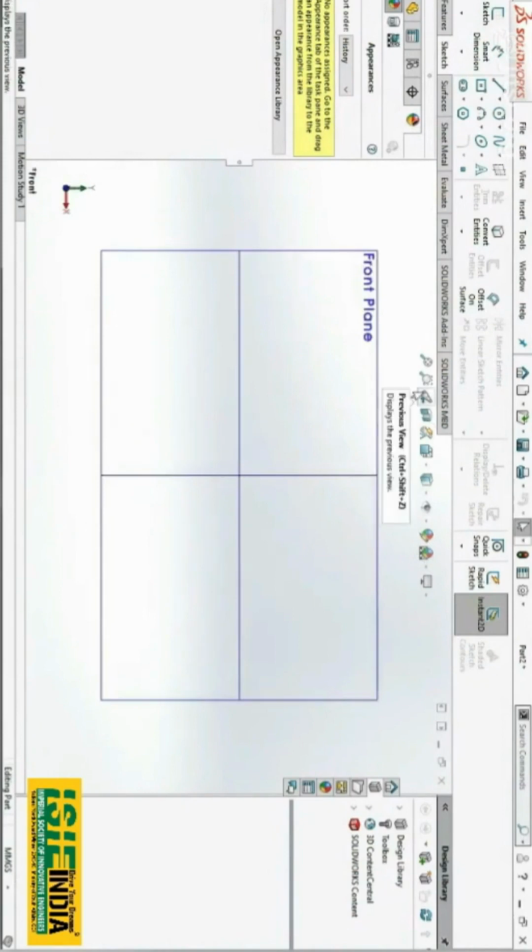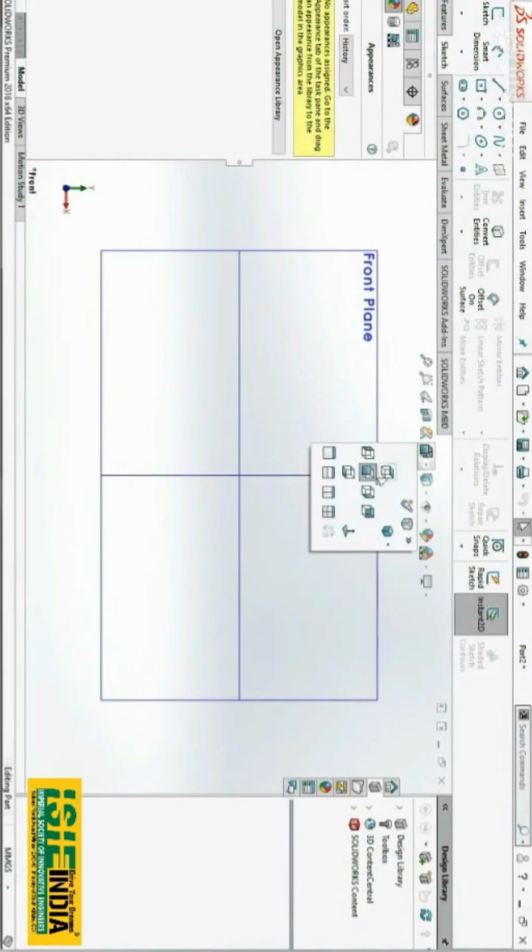The X is the previous view. So to get the previous view it was having, you can use that tool. We also have the orientation, like what I had explained, Control 1, Control 2. This is all mentioned here. So this is the isometric view. You can get the dimetric and the trimetric views as well.